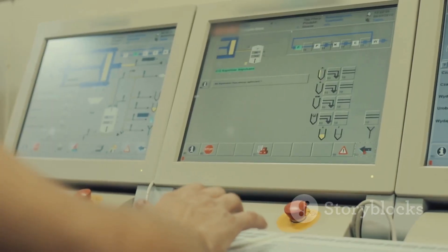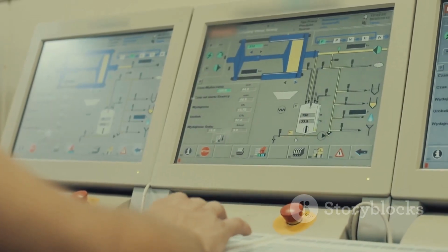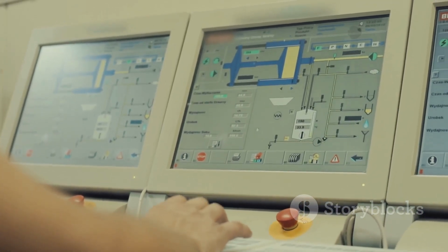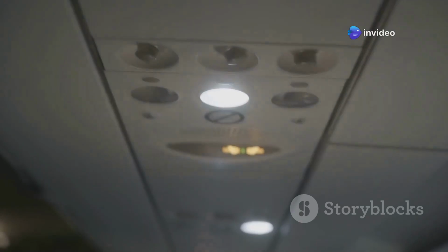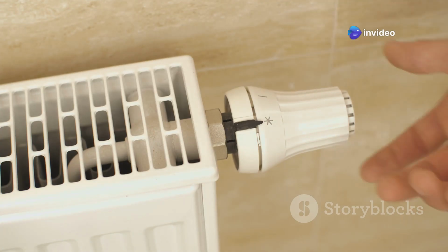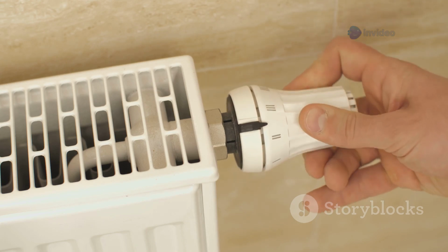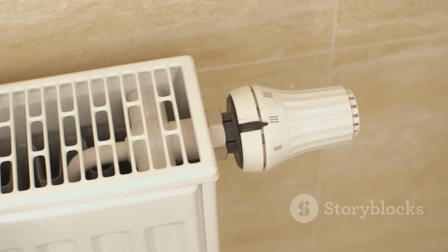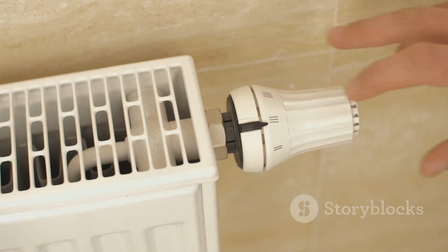The controllers, following their programmed schedules and logic, then spring into action. They command the lighting systems to turn on in occupied zones. They also signal the HVAC system to adjust temperatures from nighttime setback levels to comfortable daytime set points.